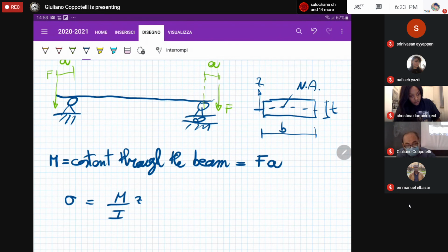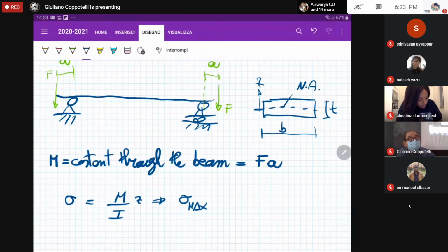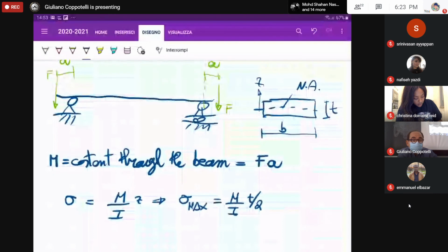That is, your maximum value of the stress because of that bending condition is given by the bending moment divided by inertia, times half of the thickness. Okay, no glue effect, no bonding device is considered. Very negligible.